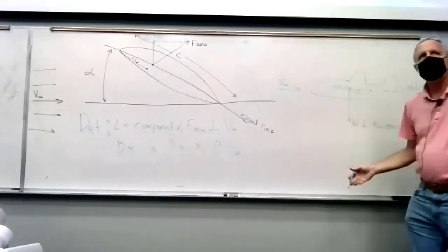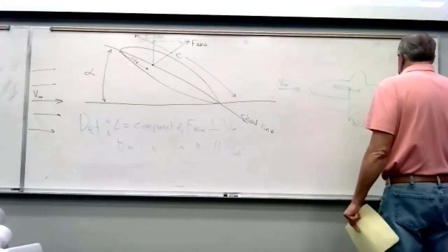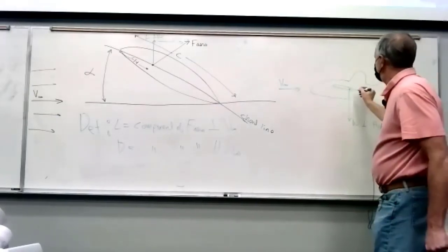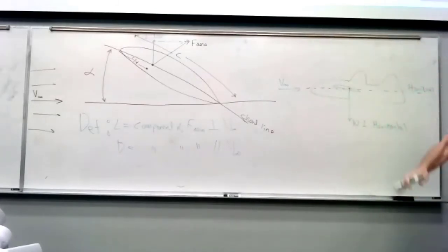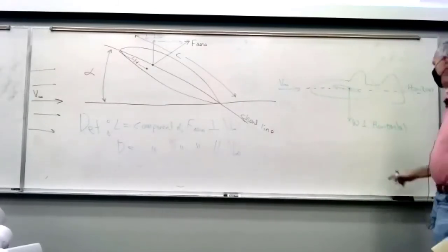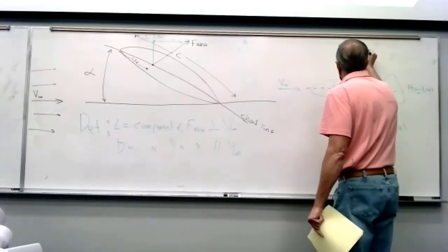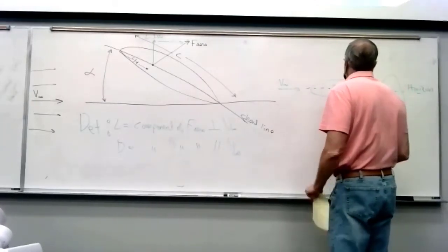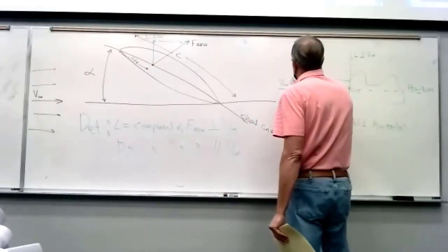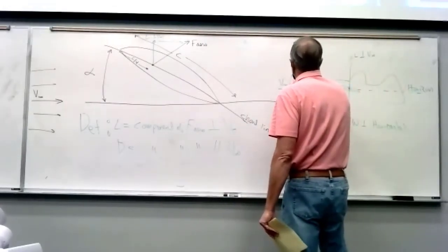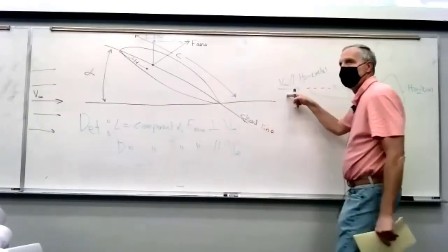That's just where gravity acts, it's down. So we have an airplane flying straight and level along the horizon, not on the horizon or you'd be crashing, but parallel to the horizon. Weight's perpendicular, and we define lift perpendicular to V infinity. And because we're flying straight level, V infinity is parallel to the horizontal, only because we're flying level.